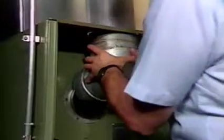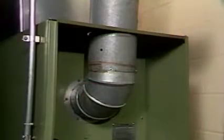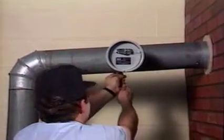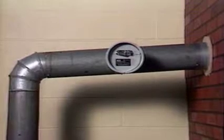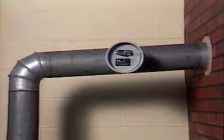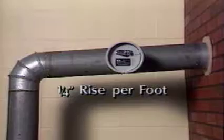Size the flue pipe the same as the breech connection pipe. Use a minimum number of elbows. In this variation, the draft regulator is installed in the flue pipe between the appliance and the chimney. Regulator pipe diameter should be at least as large as the flue pipe diameter, unless specified otherwise by the manufacturer. The pipe should rise 1/4 inch per foot in the flue run to the chimney.